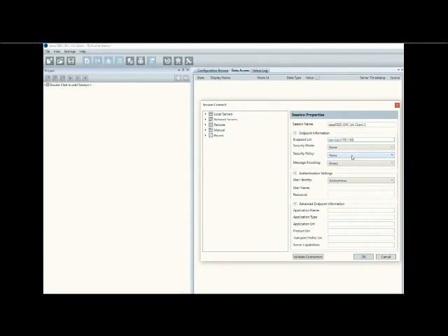And in this case, I'm actually typing in opc.tcp://192.168.50.50. That is the IP address of the gateway. The last part here, 4840, refers to OPC UA communication. That's the port. So I go down at the bottom and confirm that this port is okay, and it says yes by the green indicator.